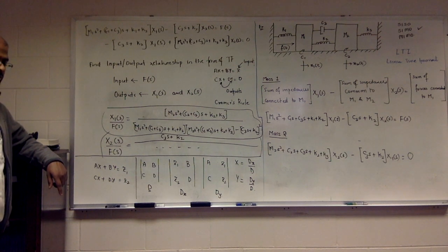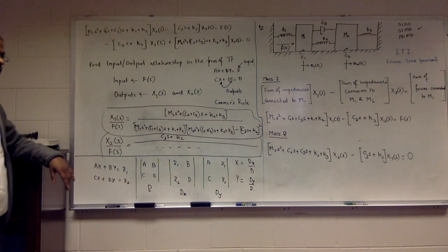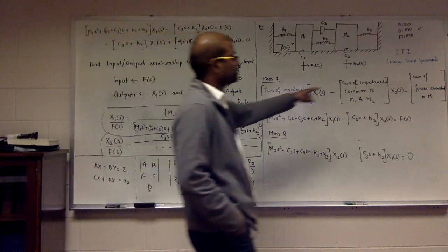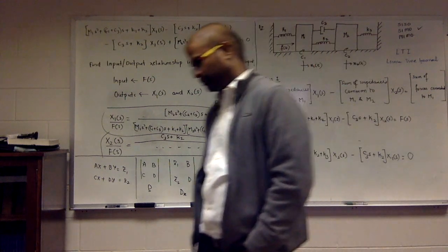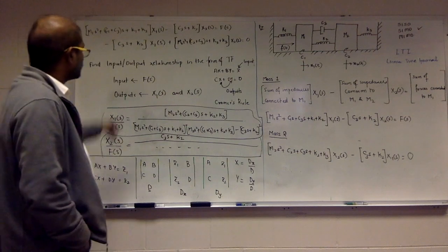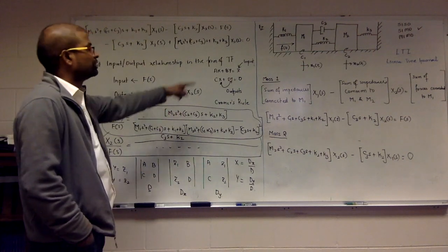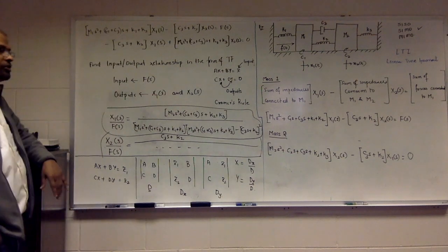Whatever basic control theory we learn in automatic flight control is applicable to linear time invariant systems only, which means the inherent property of the system does not change.